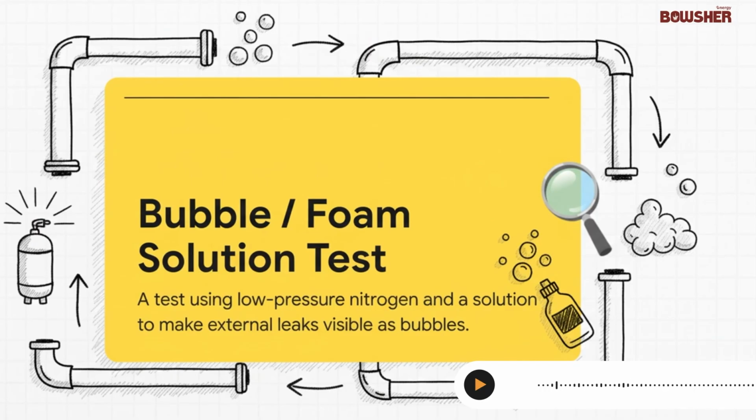First, you gently pressurize the system with some low-pressure nitrogen gas. Second, you go and apply a special leak detection solution to the outside. That's it. Simple, right? But as we're about to see, it's incredibly effective.